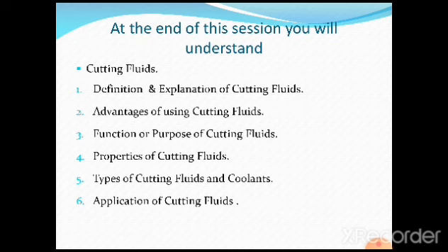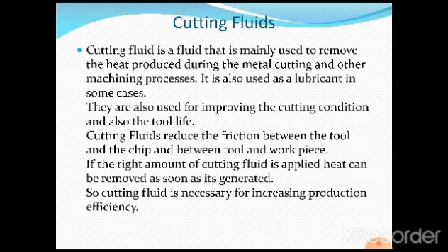So now in today's session we shall start with the cutting fluids. This particular fluid is going to play a very major role in the process of machining. In a modern workshop or any manufacturing industry, an enormous amount of power is lost either by generation of heat or by friction between the tool and workpiece. Whenever there is a machining operation, there is generation of heat due to friction between the tool and workpiece, because the tool is going to cut the workpiece and definitely there is friction. Due to friction a lot of heat is generated.